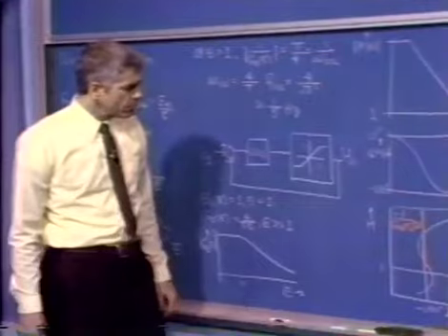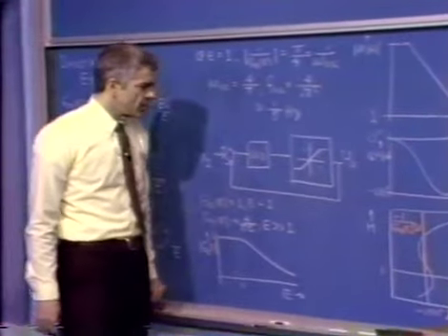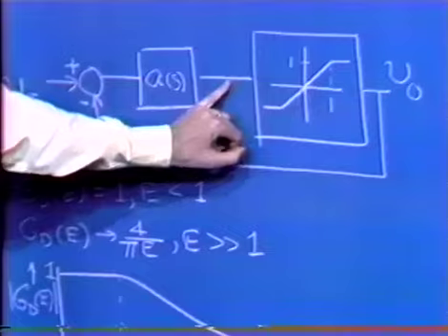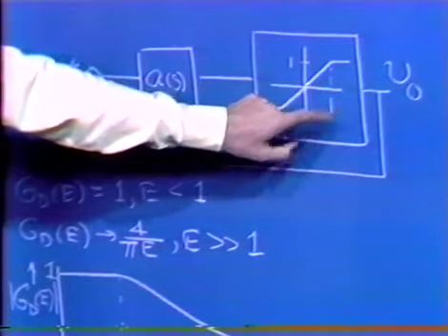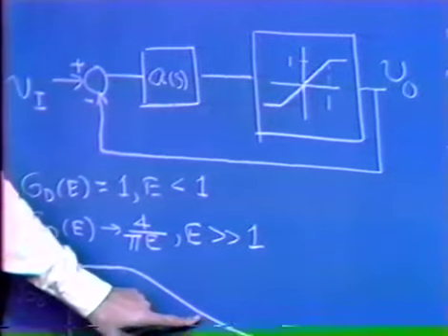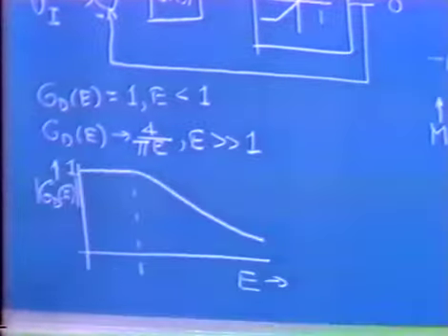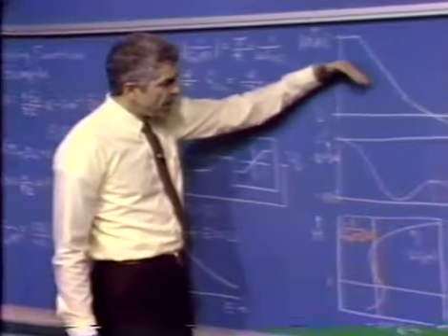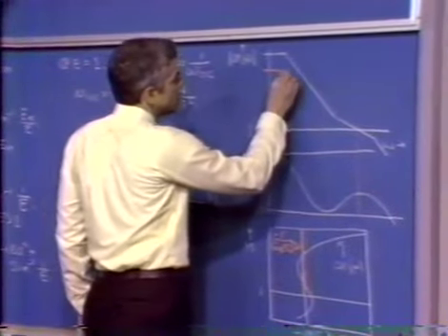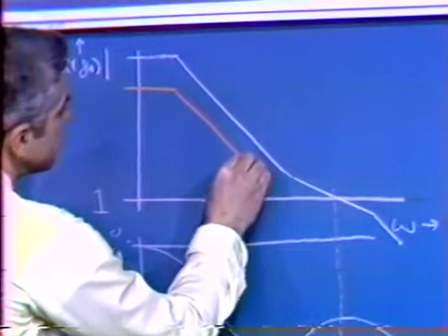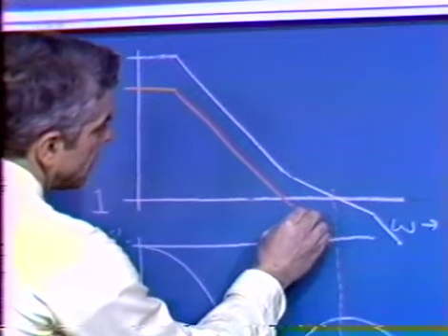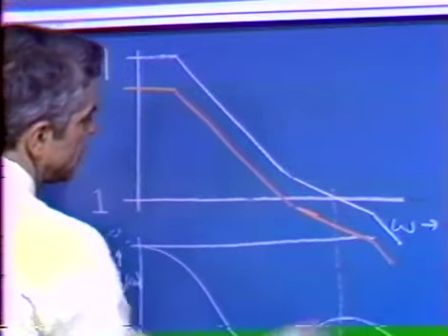Stability is determined by what happens out here, and we can certainly arrange things to have acceptable phase margin in that region. But now let's put a big signal into the system, such that we get the signal at this point larger than 1, have a peak value larger than 1. The element saturates. Its gain in the describing function sense begins to drop. And now the effect of the gain dropping is to push down our describing function loop transmission, maybe something like that, for large signals.